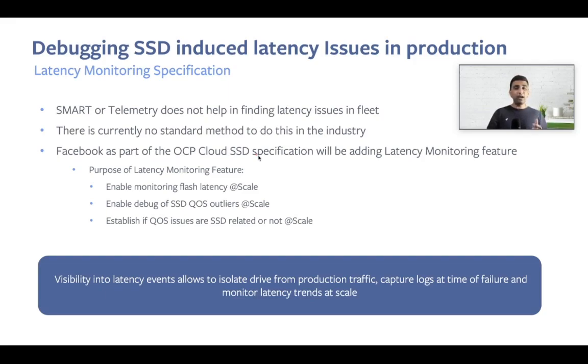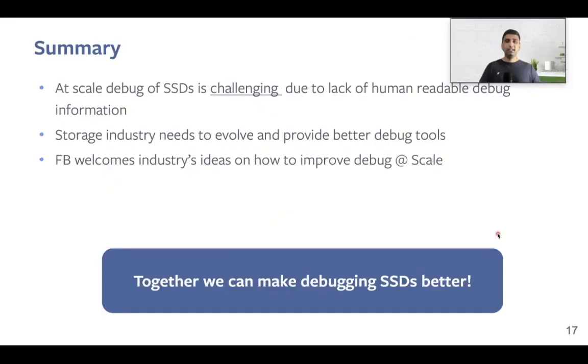Here's an example of how visibility into latency events would allow us to isolate the drive from production traffic as early as when the event happens, would allow us to capture logs at the time of failure, and also allow us to monitor latency trends which are happening at scale. This is just one example of how improving the logging around understanding of SSDs could make such a drastic improvement and change in debugging of SSDs in production environment.